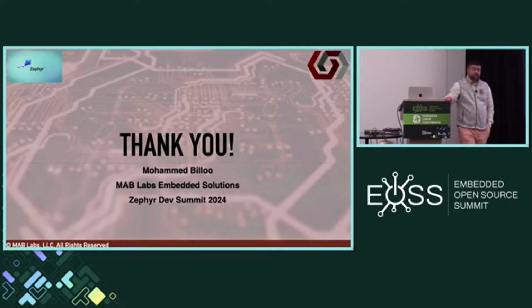Yeah, I had the same issue when I was talking yesterday about VirtIO MMIO. When you have that running underneath, you can run RPMsg on that, but that's fixed size and small units. But next to it, you can expose a VirtIO network interface, for example. And then you use shared memory next to RPMsg instead of over RPMsg.